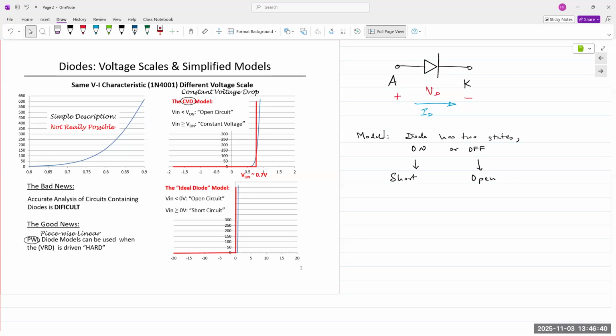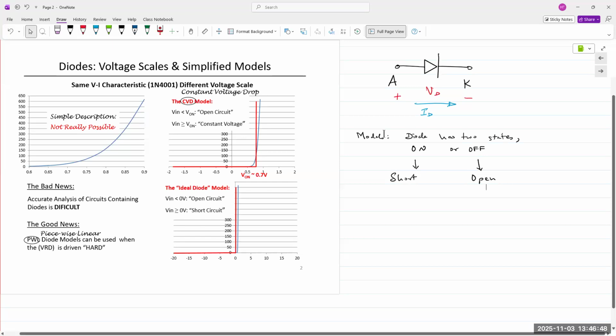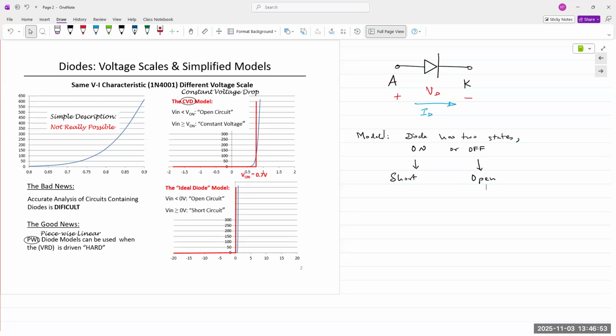Okay. All right. So now what happens when a switch is turned on? If the switch is turned on, it allows a pathway for current to flow through. Same thing for a diode. If the diode is on, current is flowing through the device. So diode current ID must be greater than 0. Okay, diode current ID must be greater than 0. So you have two terminals, and if there's a short between those two terminals, current is flowing, so it must have a positive value.